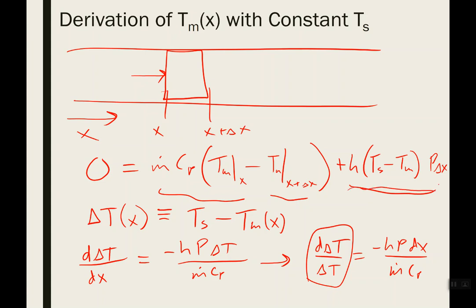So what we found was that at the beginning of the pipe, there's the biggest delta T. So delta T would be the difference between our pipe surface temperature and our fluid mean temperature. So that large delta T means you're going to get the highest flux right at the entry of the pipe. But then as the fluid starts to heat up, your driving force, your delta T, gets smaller and smaller, which means you get less and less heat added each time.